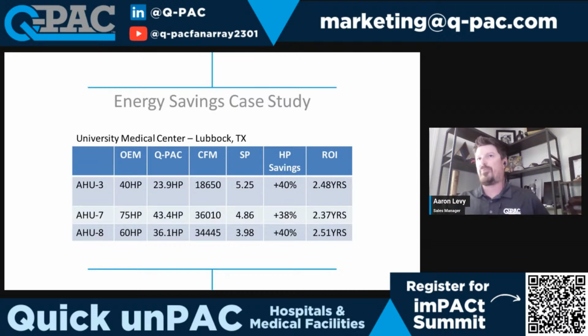Looking at something like a Baldor or a Marathon or a WEG motor, those motors will say on the data plate they're somewhere between 88 to 92% efficient, but that's at full load. They don't know what they're putting on the front of that motor. It could be a pulley, it could be a wheel, it could be a pump for all they know. So now you've got a motor from one manufacturer, a wheel from another manufacturer, a hub or a sheave, belts. So you've got all of these losses that come through your system: transmission losses, drive losses, electrical losses.